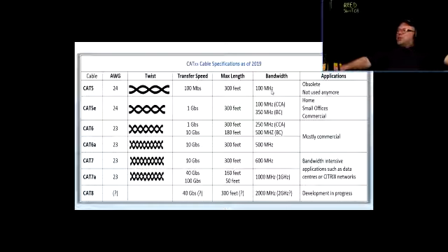This is the maximum frequency at which you can send an analog signal through that cable and the signal is still understood on the other end. Okay, and the maximum length of that Cat5 would be 300 feet. Actually, to be exact, it would be 328 feet. However, it is just taken that 300 is easier to remember, and you try to stay away from the 328 feet end to end, because you still are going to have things like connections, terminations, and maybe patch cords and stuff like that.